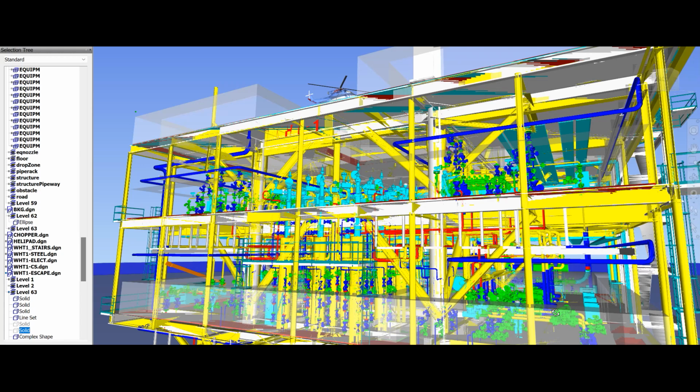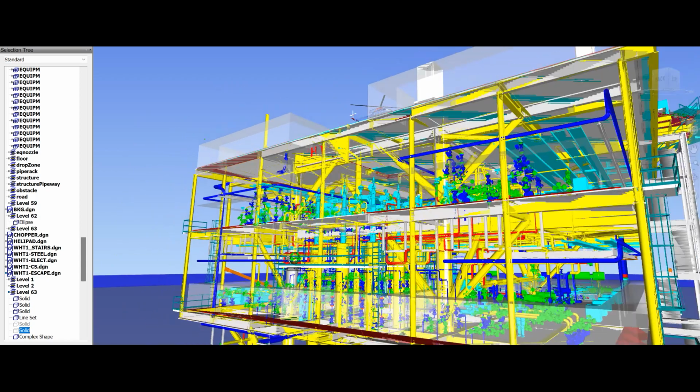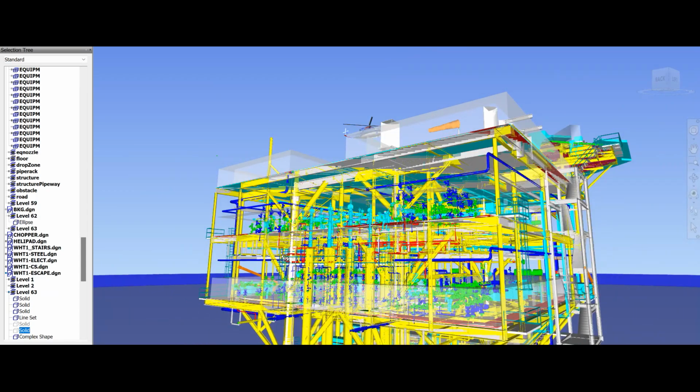And then the production header has 2-3 more things like sample connection, injection coils, corrosion rate, CC and CP connections. And from the production header, it is connected to the launcher. In many platforms, and in a few platforms there is no launcher, then it is directly connected to the dropout spool.